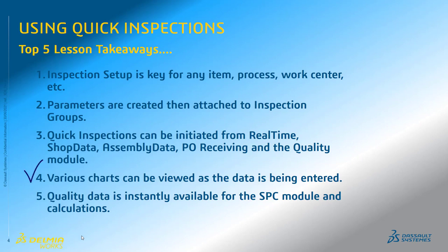Fourth, various charts can be viewed as the data is being entered, and I think we saw that when we were plugging in our data for our lengths or our widths on the inspection that we showed. We saw that we could view the data after it's been entered, and we can actually view the data as it's being entered on a real-time basis. And then lastly, quality data is instantly available for the SPC module and the calculations in that module. There's no manual transferring of data from the quality inspection to the SPC data. That module automatically has that data available and starts the calculations for your additional quality analysis.